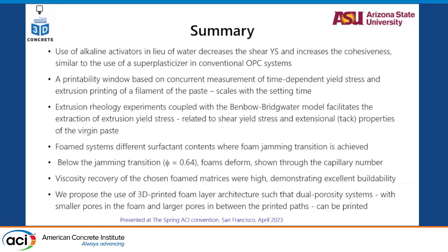So in summary, we have used alkaline activation as a way to decrease the shear yield stress and increase the cohesiveness, similar to the use of superplasticizers. Very nice parallels with what you get when you use a high range water reducer for your conventional paste.